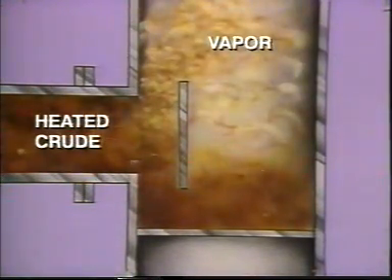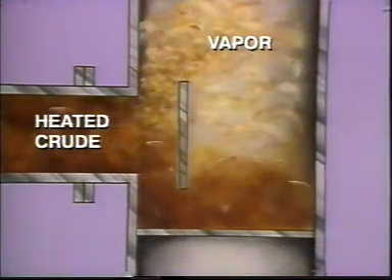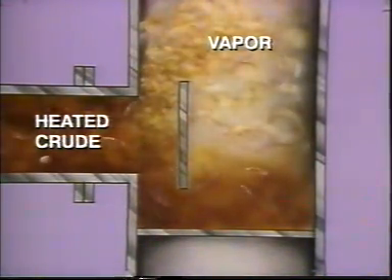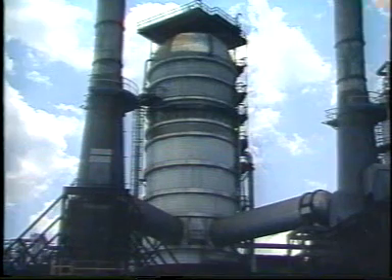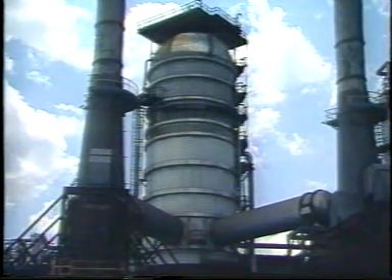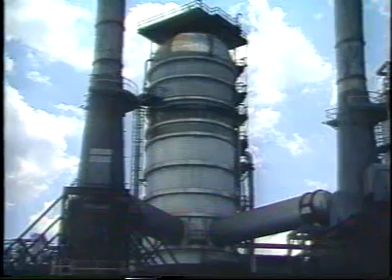The reduced pressure allows the lighter components to flash out or vaporize the moment the feed is introduced into the column. Vacuum towers must be able to handle high vapor loads, so they are usually designed wider than other types of towers, and their trays are spaced further apart.